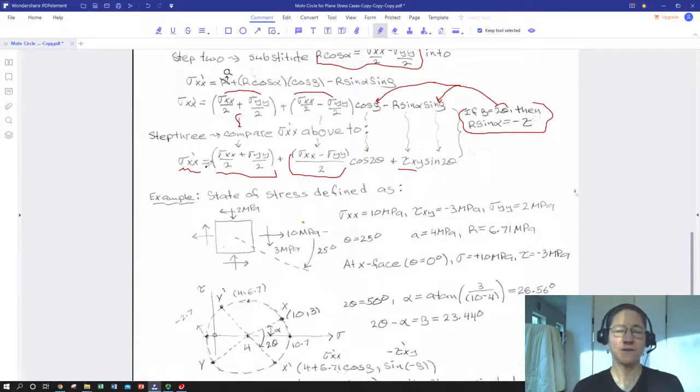So this is a Mohr circle friendly version of the stress transformations. All we did was some mathematical wrangling, basically. And now we've kind of gone backwards. When we derived the Mohr circle expression, we said, hey, we don't want any terms that have a theta. We want to get rid of those in order to show that this looks like a circle with a center and a radius defined in terms of something I know.